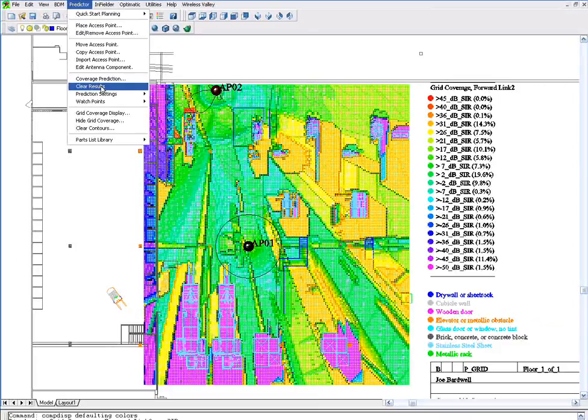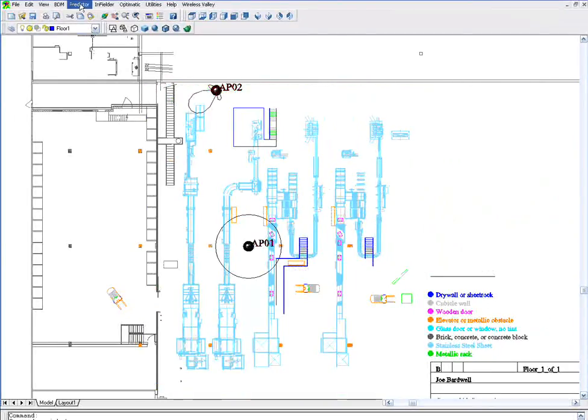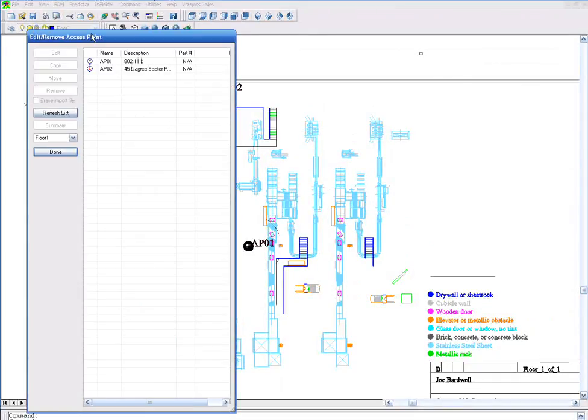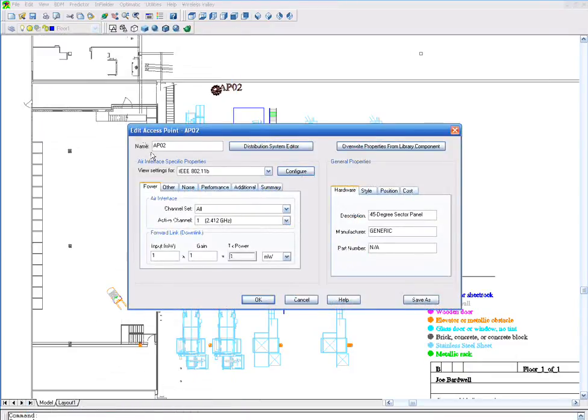With a simple reconfiguration in the RF CAD modeling and simulation system, we can move the access points easily and change any aspect of their configuration. In this way, configuration changes, just like physical location changes, can be simulated in the virtual space before going on site to actually do an installation or a configuration. So we move the access point from channel 1 to channel 6.